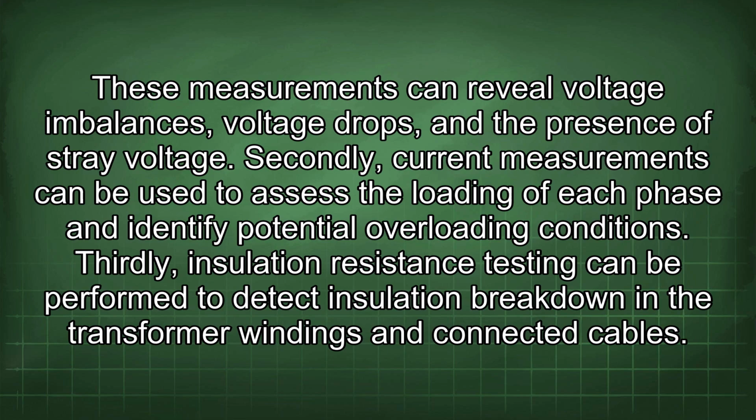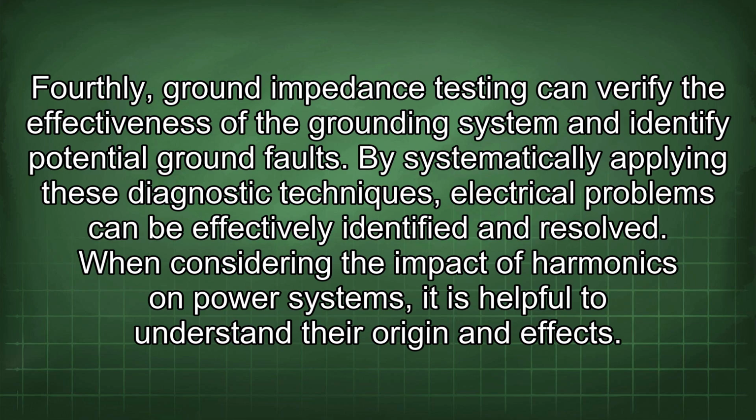Thirdly, insulation resistance testing can be performed to detect insulation breakdown in the transformer windings and connected cables. Fourthly, ground impedance testing can verify the effectiveness of the grounding system and identify potential ground faults. By systematically applying these diagnostic techniques, electrical problems can be effectively identified and resolved.